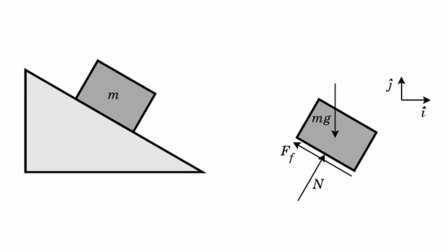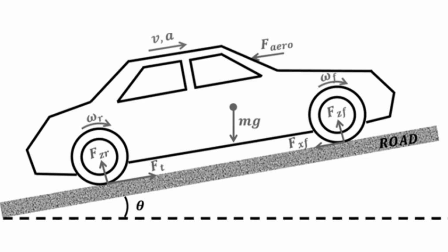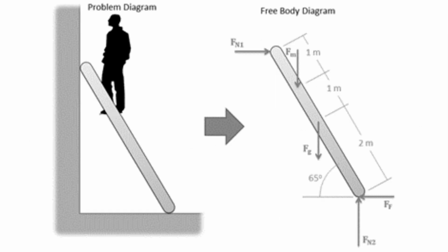Free body diagrams. When problems involving the equilibrium of bodies under the action of force systems are being solved, a method of setting out the essential details in the form of a diagram is necessary. We often start with a semi-pictorial sketch or space diagram showing the physical conditions of the problem, for example, a layout of the mechanical or structural components such as pulleys, supports, cables, rollers, etc. The next step is to isolate the essential facts about the forces involved and to draw a free body diagram.